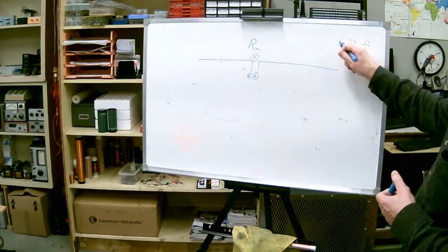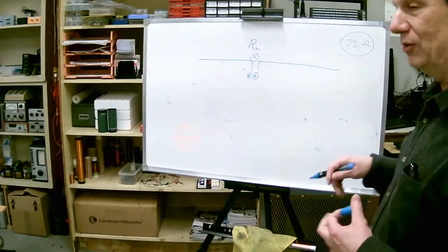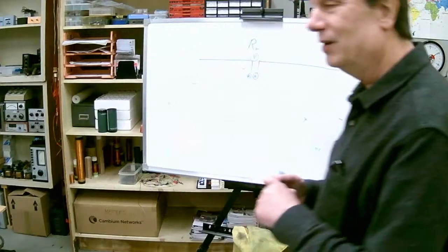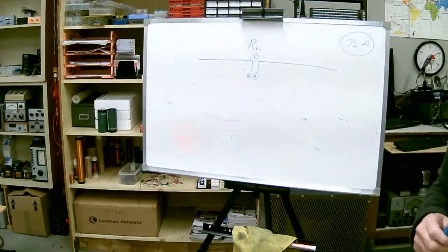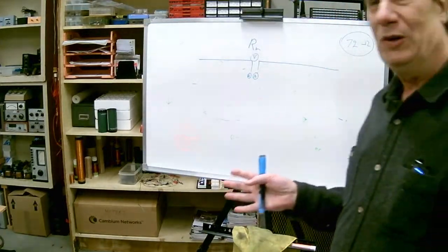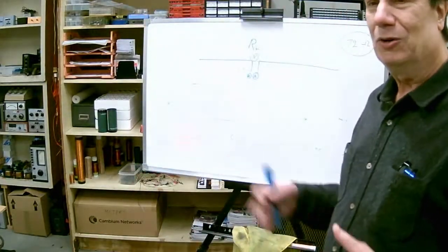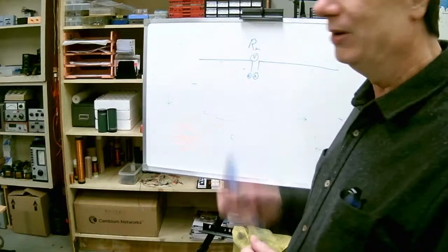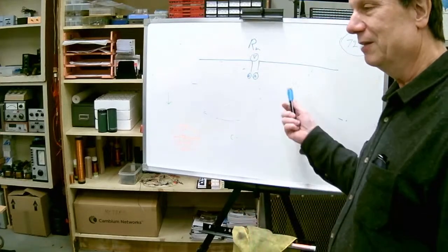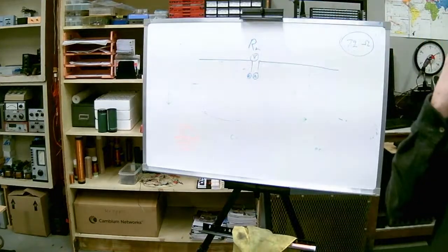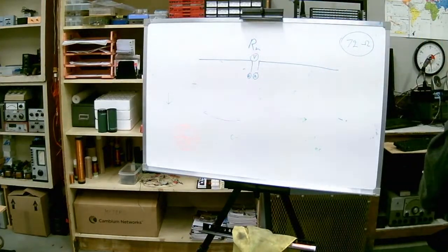But the number to remember now, when we get antennas to practical heights, it generally tends to lower the impedance. The reason so much of your radio frequency equipment is designed for 50 ohms is because antennas in most practical environments are usually quite a bit lower than 72 ohms in free space. But that's in free space. Any questions?